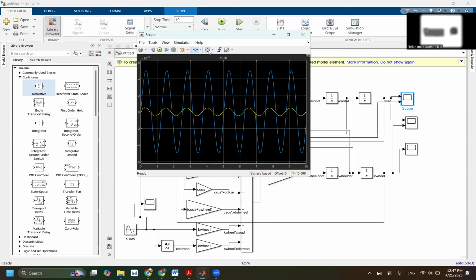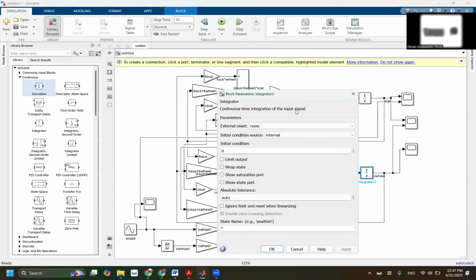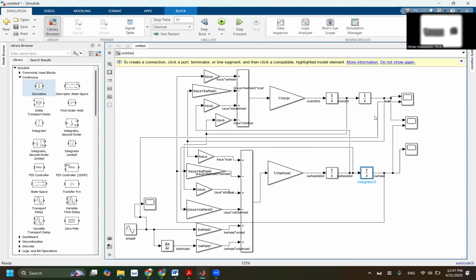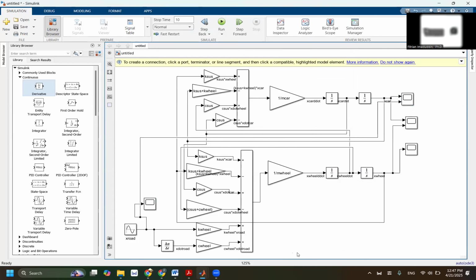Any other answer? Remember, what classification is this? Free vibration or forced vibration? If this is free vibration, if I don't put any initial condition, nothing will happen. But I put all initial conditions equal to 0, and this is still a vibration. So it cannot be free, it has to be forced. But I don't have an external force working directly. Yes, that's why this